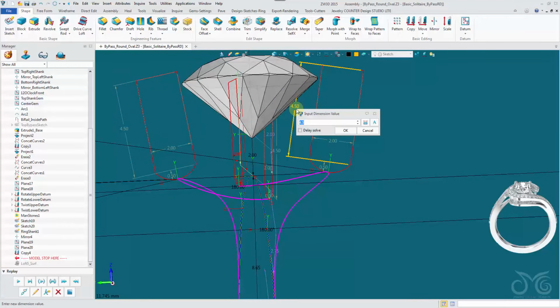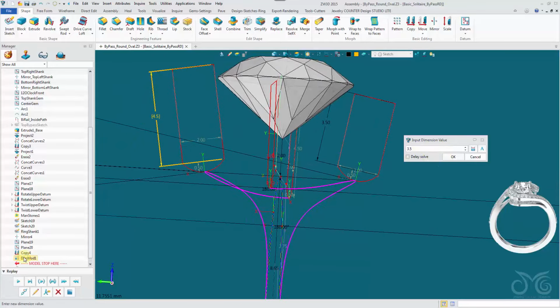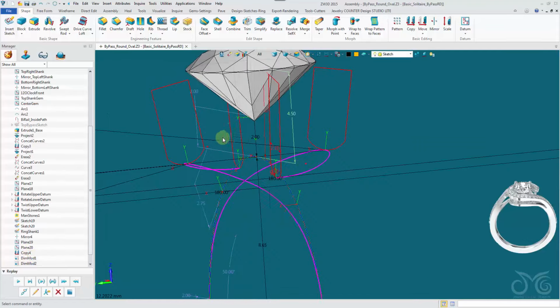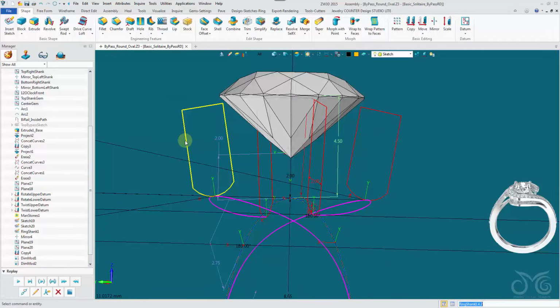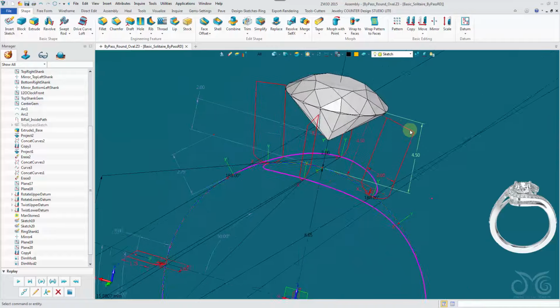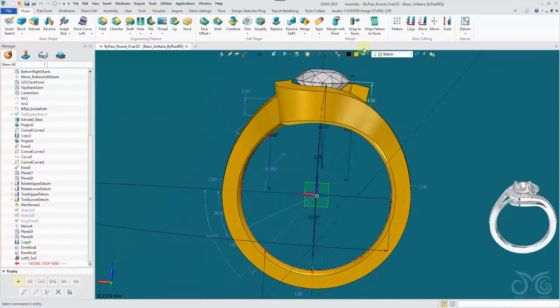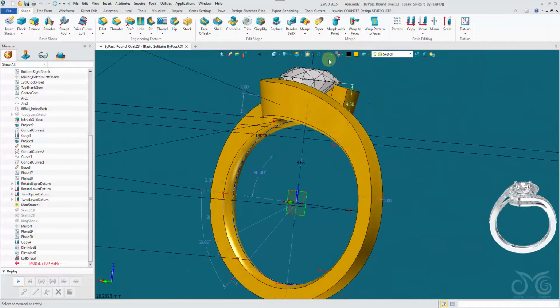And you'll see, if I hover over this one, that when we are changing the dimensions after a copy, so these are copied sketches, you'll see that dimension modifier added into the history. Because they're copied sketches, they cannot be updated throughout history as having that dimension because they are originally copied from the 4.5. So we'll play the loft. Again, that's a nicer shape there. We're keeping a good flow.